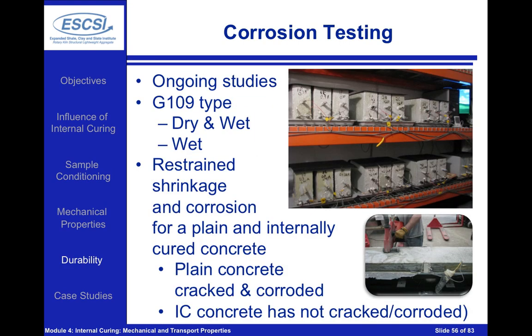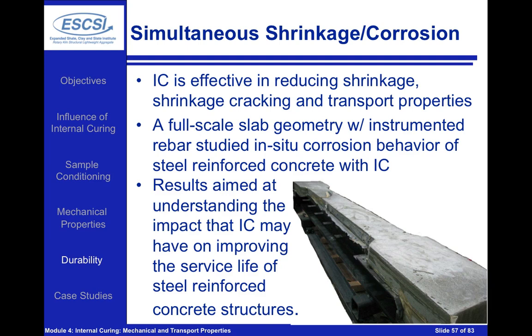Corrosion testing, this has also been widely undertaken, but one of the things that I want to point out here is that generally if we run just straight corrosion tests, we see a slight benefit of the internally cured concrete because of the denser concrete, because it's harder to transport through the system. But what I really want to talk about is what happens when you have the corrosion potential taking place in a plain concrete that can crack and corrode, and an internally cured concrete exposed to the same types of conditions.